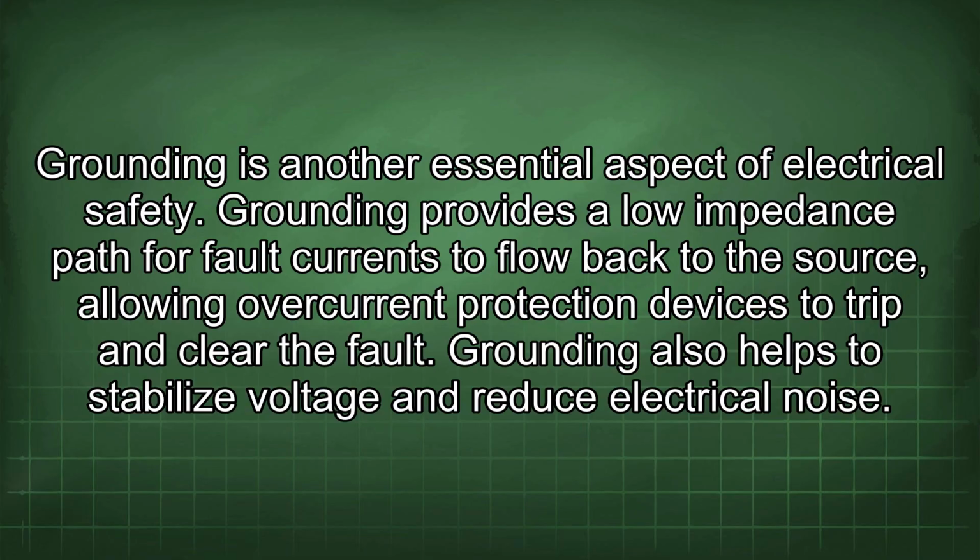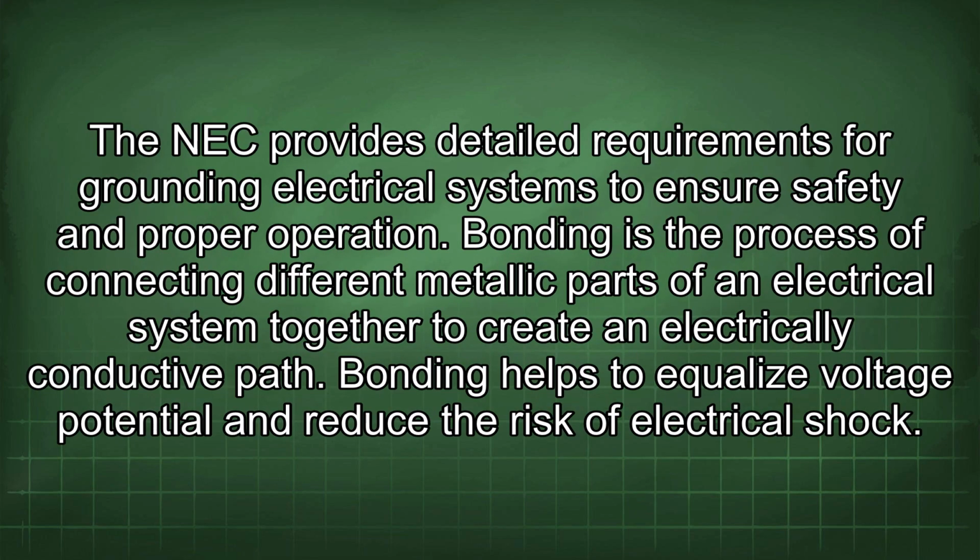Grounding also helps to stabilize voltage and reduce electrical noise. The NEC provides detailed requirements for grounding electrical systems to ensure safety and proper operation. Bonding is the process of connecting different metallic parts of an electrical system together to create an electrically conductive path. Bonding helps to equalize voltage potential and reduce the risk of electrical shock.